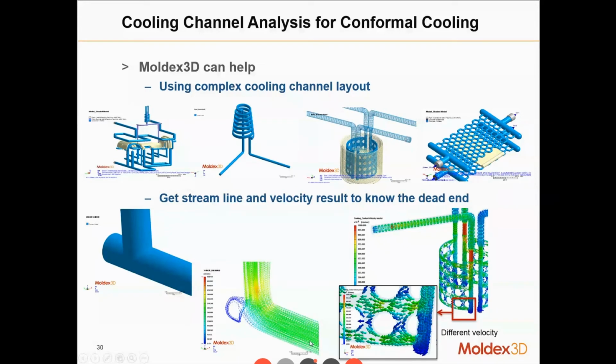As you can see, most of the water in this cooling channel is flowing in this direction, and hence creates what we call a dead water zone. The speed is horribly low, and there is no water coming in and out in this area, so it creates a poor cooling effect.